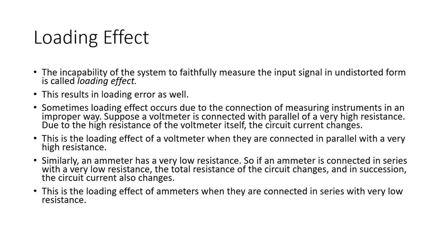Loading effect is a cause of this gross error. So what is loading effect? Loading effect is the incapability of a system to faithfully measure. So a voltmeter cannot faithfully measure a high voltage if it is designed for a low voltage. Similarly, an ammeter cannot measure high currents if it is designed for low current, or it cannot even measure low current if it is designed for high current. So low current would be neglected by that ammeter.